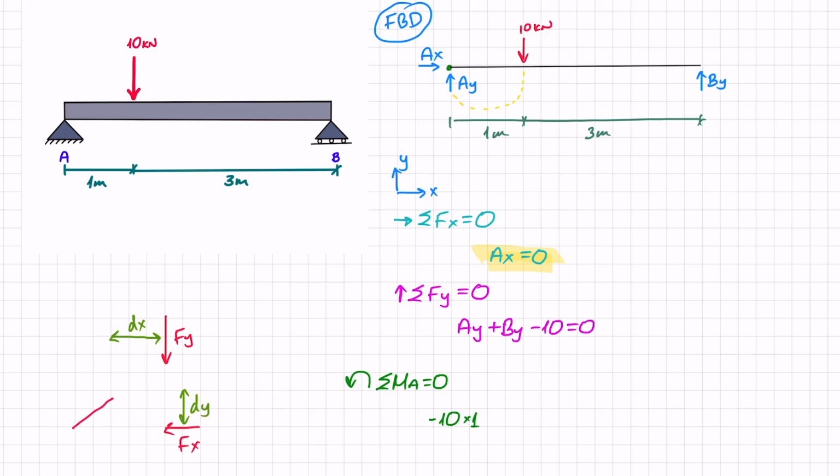If I have a force that is xy, say this force here, the distance, since this has to be the shortest distance, which is the perpendicular distance, is also going to be in the xy plane. And that is why I find it very useful to just divide into components, because you always know that if you have a y component, you need an x distance, and if you have an x component, you need a y distance. And we'll cover that in the future.